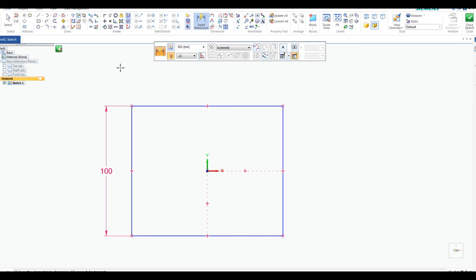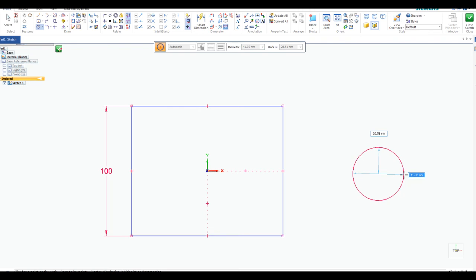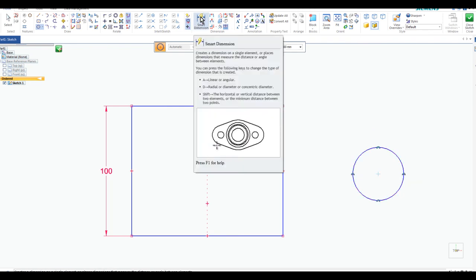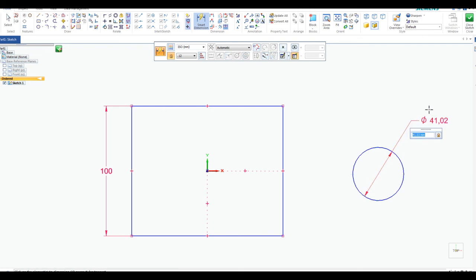Okay. The next thing I need to do is create the back end here, because this is theoretically not a regular shape. So the back end, the rounded end, is a radius of 15. So that means that we're going to need a diameter of 30. So I'm going to just use my circle command. I'm going to pick, again, approximation, select, and then I'm going to put a dimension to tie it down. As always, in this case it's 30 millimeters. Okay, so I've sized the circle.